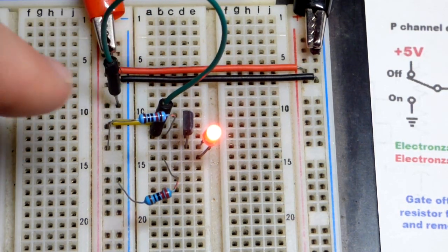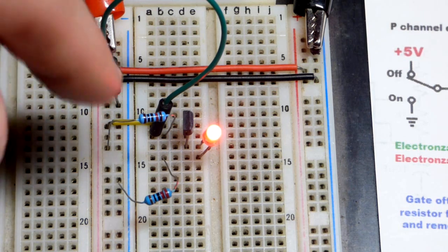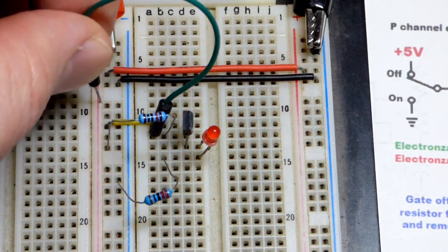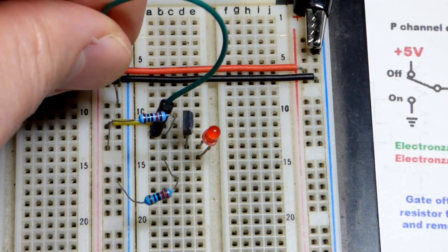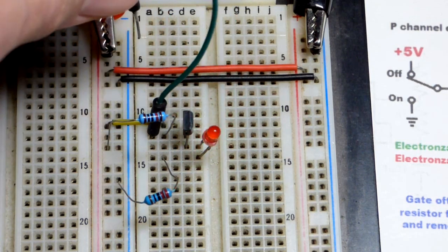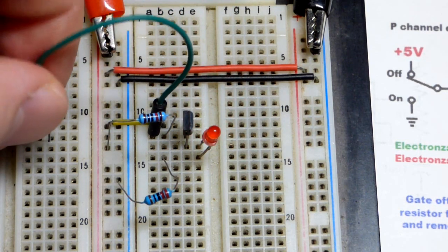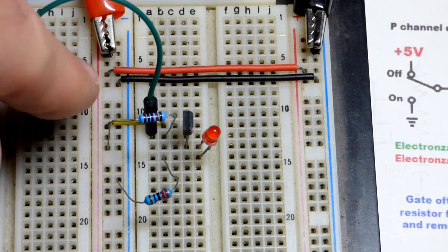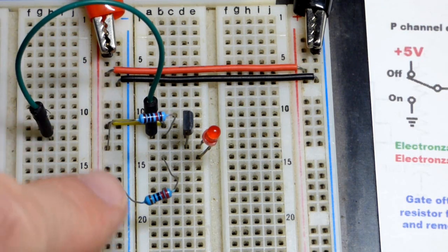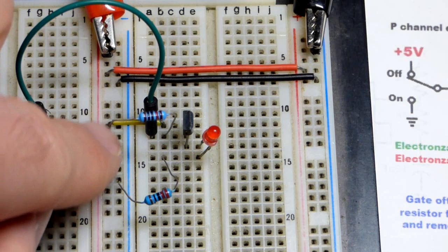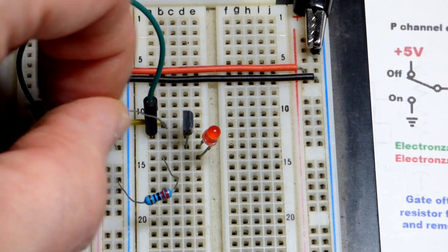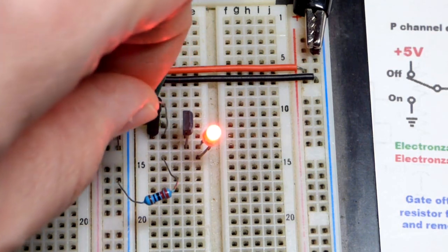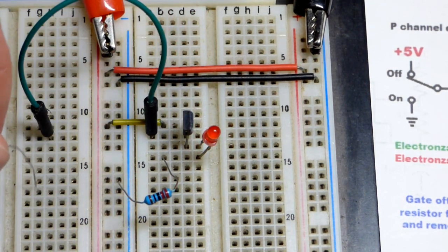Sometimes not all outputs of stuff have both the negative supply and positive supply as their output, which is the input for this. Sometimes, you might either be connected to ground or off, which you can do with the mechanical switch. They commonly either connect to one supply rail, or they're just drifting in the air and off. So then you would definitely want either a pull up or pull down resistor. So that's pull up. In this case, that keeps the transistor off. Pull down keeps the transistor on. So be aware of that.